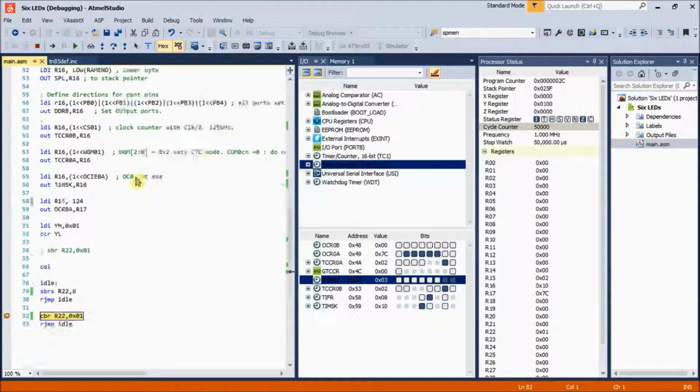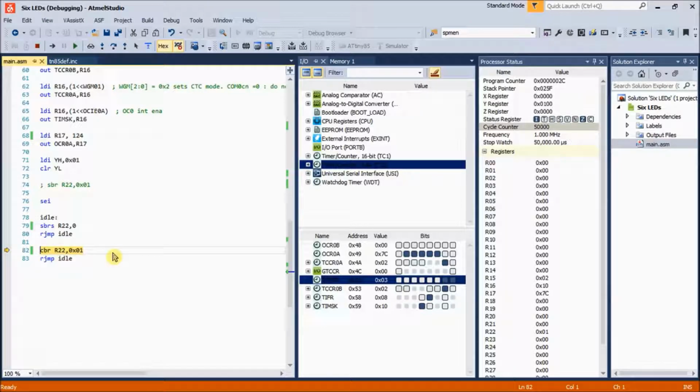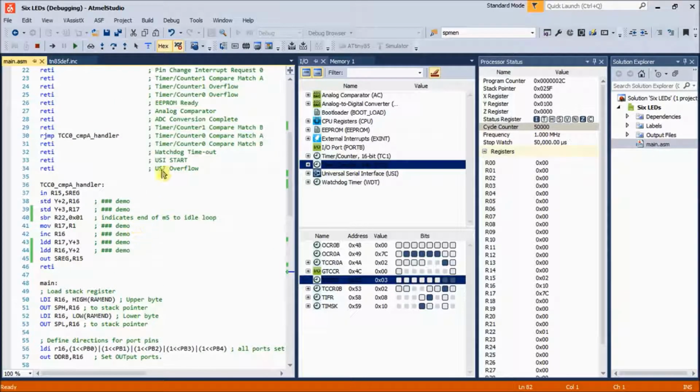Now then, I'll take that reset away, that breakpoint away, and I'll put a breakpoint in the routine here, because I want to step through this and just show you the stuff that I put in for demonstration. It is convention that registers 16 and 17 are used as general purpose registers. There are a few conventions about how you use registers.